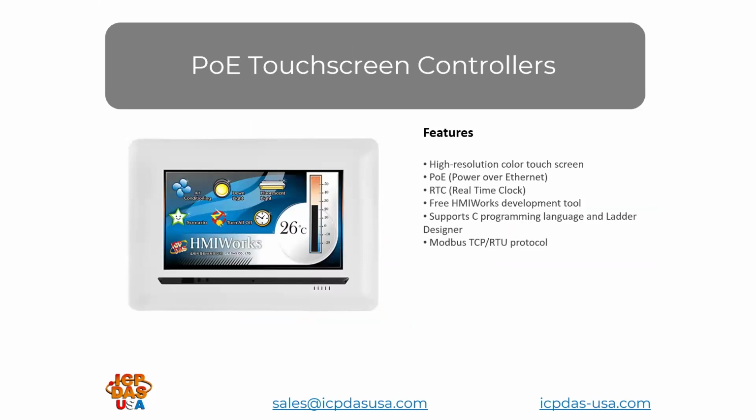We offer PoE touchscreen controllers. Specifically shown here is our TPD 703. This one communicates using Modbus TCP or Modbus RTU to remote devices like HMIs, sensors, or remote I/O modules to bring in data, and it can display and control the devices connected to it from Modbus RTU and TCP, and it's got a real time clock built in, and it supports C and ladder programming done using our HMI Works software.